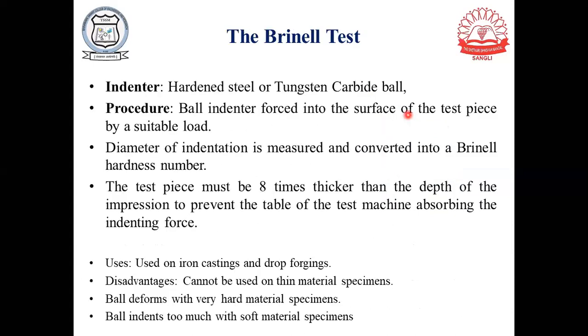This is the procedure. Take an indenter ball made up of hardened steel or tungsten carbide. Then, using the hardness testing machine, this ball indenter is forced into the surface of the specimen. I will simply show how it is done.